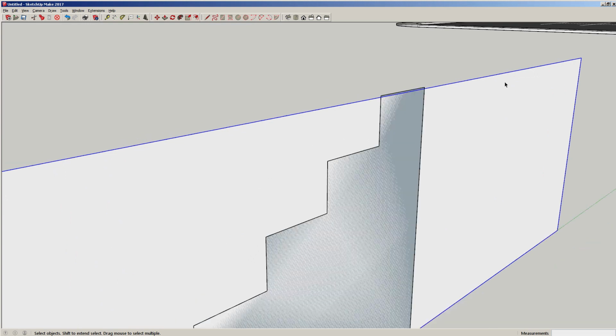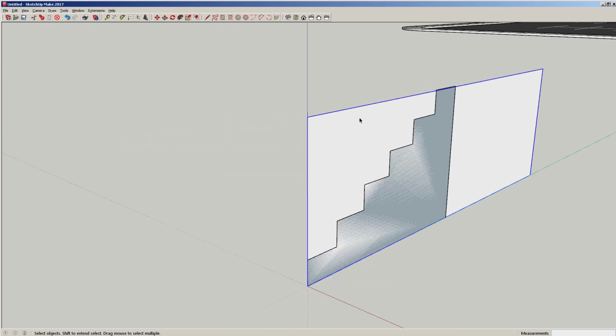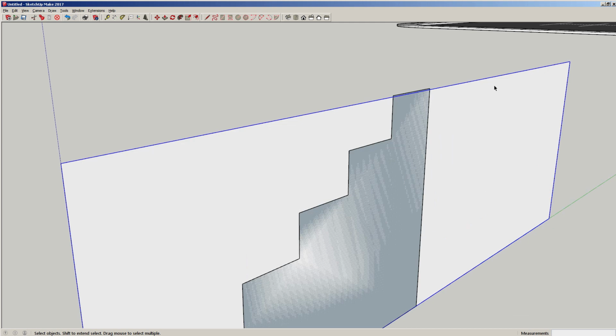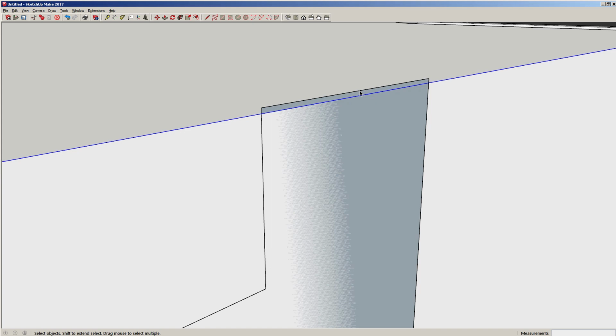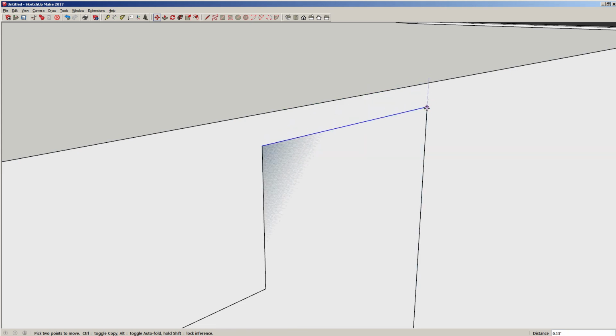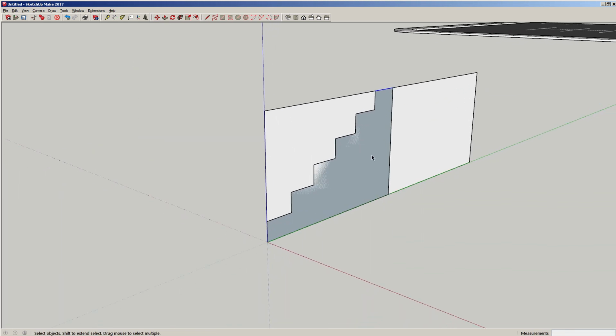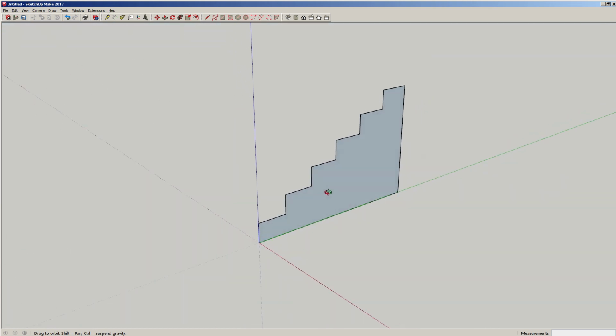But we are going to have a problem trying to place this next to other elements that you made 4 feet high, like a quarter pipe, a ledge, a bank. So we can actually cheat and click once on this top line, press M, snap to the corner. We're going to go down. Remember, while it's on that blue axis, you can hold shift to snap it, so your mouse won't throw it off the axis, and just click on the top of that face. Of course, it's not exactly 0.67 or 8 inches high, but that's okay. This is concept. You get the idea. There's some stairs.